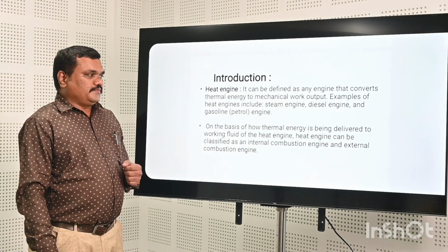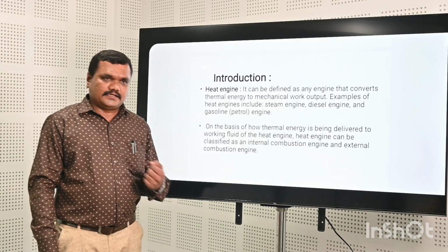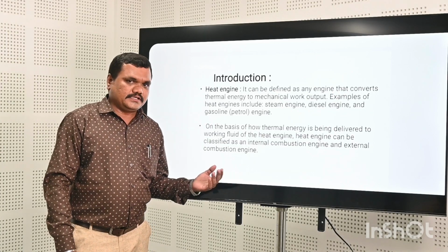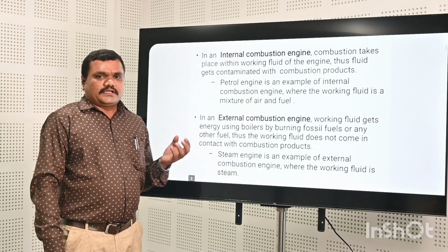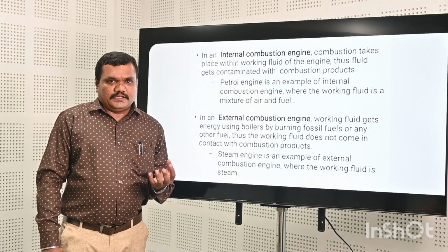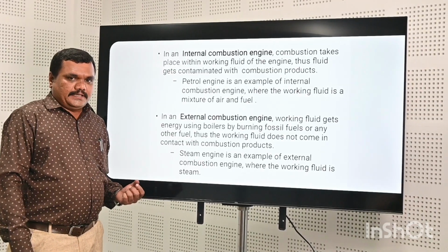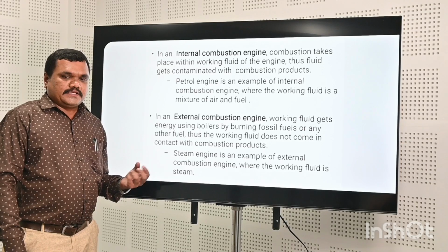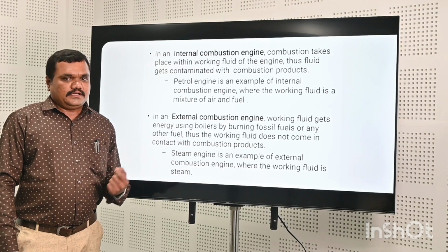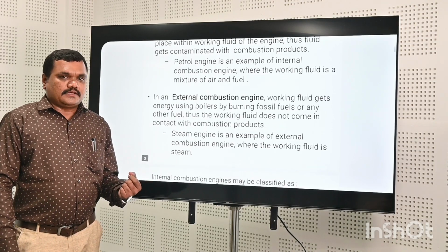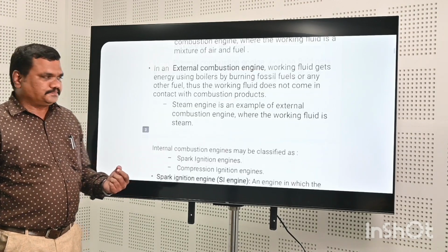Based on how the thermal energy is delivered to the working fluid, a heat engine can be classified as an internal combustion engine or an external combustion engine. In an internal combustion engine, the combustion process, that means the burning of the fuel, takes place inside the engine cylinder. Whereas in an external combustion engine, the combustion process takes place outside the cylinder. The best examples for the internal combustion engine are the petrol engine and the diesel engine. The best example for an external combustion engine is the steam engine.